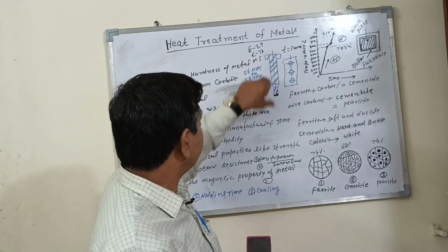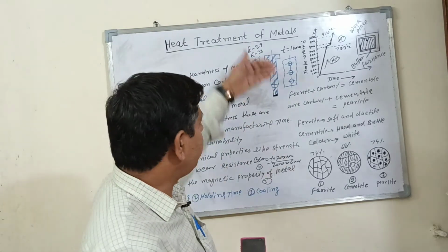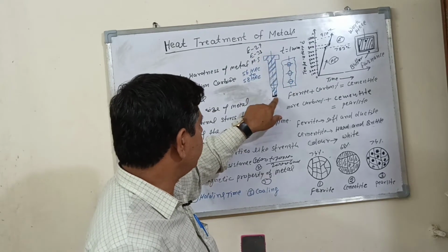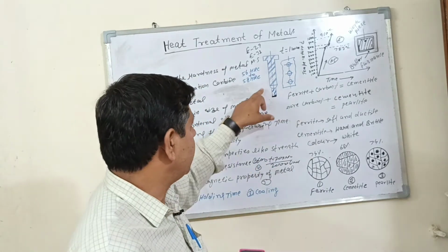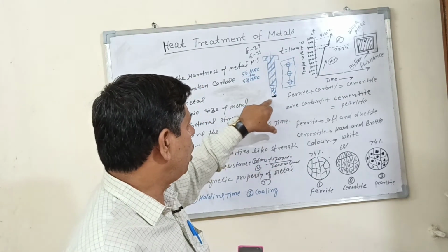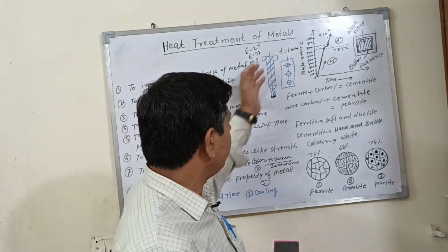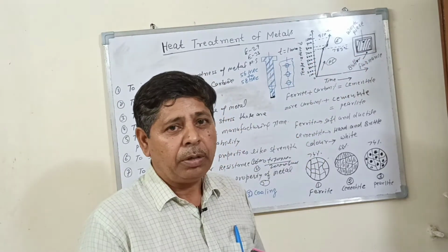The material of this punch will be selected as MS, EN29, EN31. So after punching a number of holes, the edge of this punch will break due to the softness and ductility of the material. So how to remove this problem? So we go to another process, like hardening.